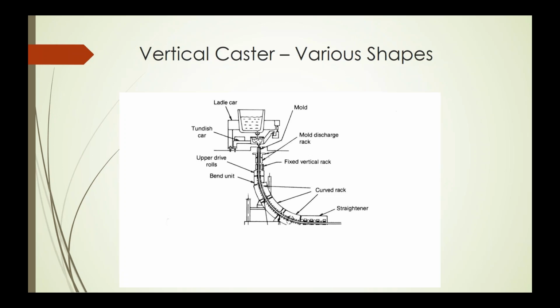They need to be various holes and or other things done to make it into the final piece or pieces. But this is a technique that can be used for very high speed, high productivity, and a wide variety of alloys. Now, it has to have a relatively narrow range of freezing on the alloy for this to work.